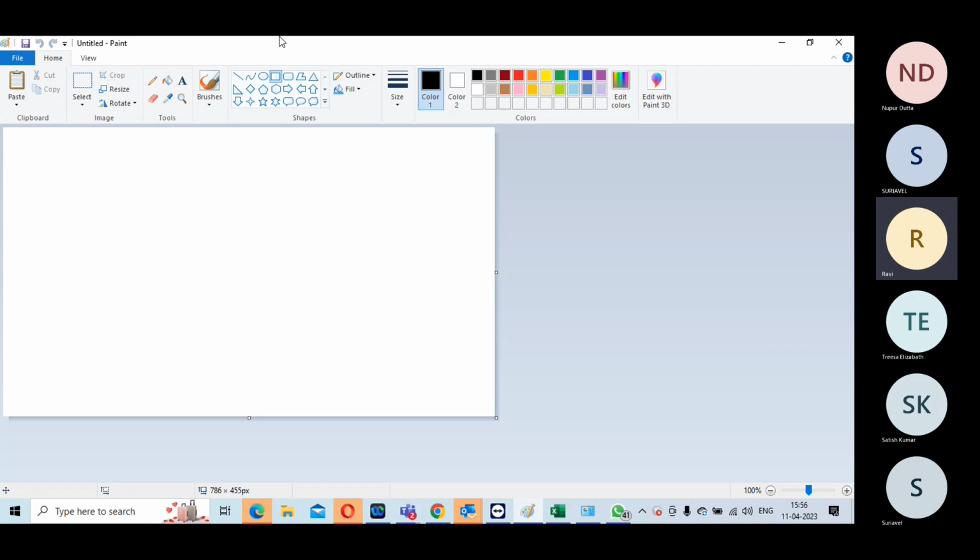Placement also, how you will run? You will run multi-mode, multi-corner whenever you are doing MMMC. You can run func mode, then it will run test mode, etc. So same thing, you will build the CTS first for the func mode, then you will append the test mode. You build some smaller trees, you build the main tree, the main root. If you want to control, you can build a clock tree. You can do single point CTS, multi-point CTS.